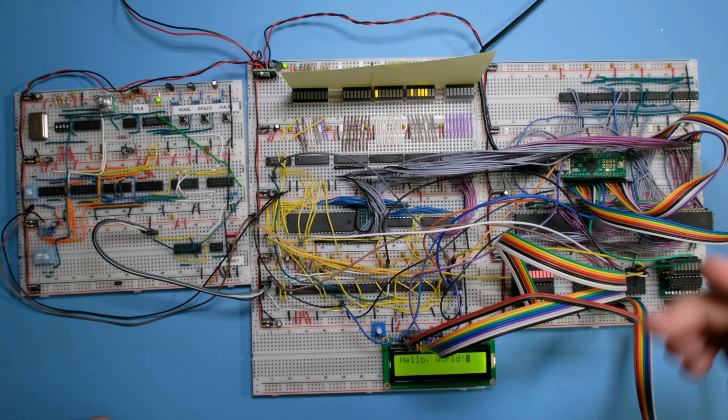So anytime I'm connected to the debugger, this clock will be disabled and the Teensy will take over. But if I'm not connected to the debugger, the Teensy will not tri-state this clock, and I can use the manual interface to work. And so I think that's going to be a better way of designing it. But we do need an additional control line on the Teensy, and so I need to solder that header now.